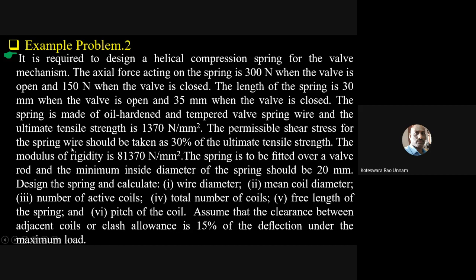Now, why this is somewhat different from the previous problem is that he has given two forces acting on the spring. One force is 300 newtons when the valve is open, and when the valve is closed, the force is 150 newtons. But while discussing the design procedure for the spring, the first thing we need to identify in any spring design problem is the maximum force on the spring and the deflection corresponding to that maximum force.